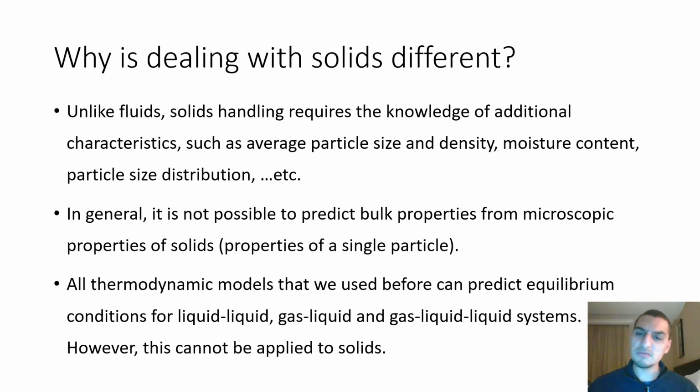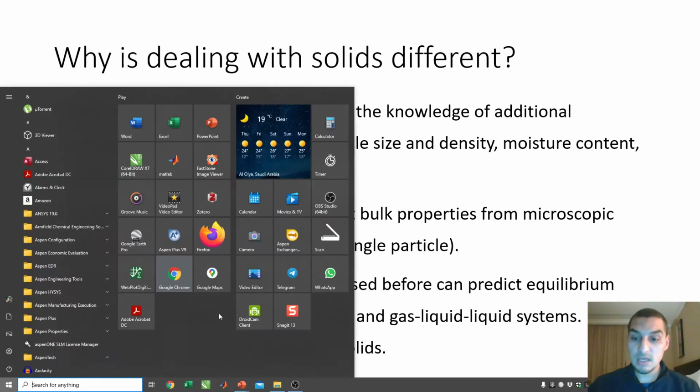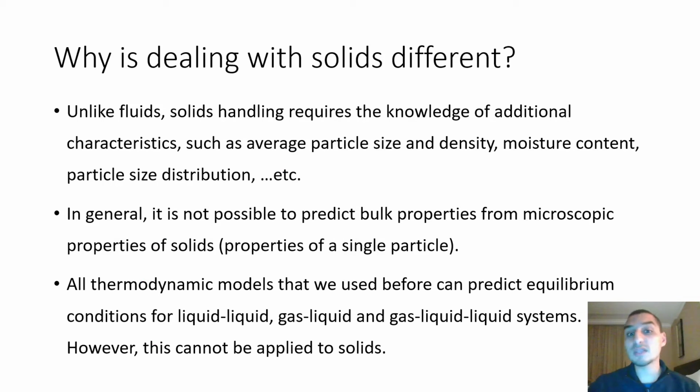And that's why, for those of you who studied unit operations, mechanical unit operations, they will remember that we mentioned something called the bulk density. The bulk density and the particle density. There are two densities for the solids, which is a result of having some pores inside the solids, and the pores depend on the particle size. So this is something that you have to keep in mind.